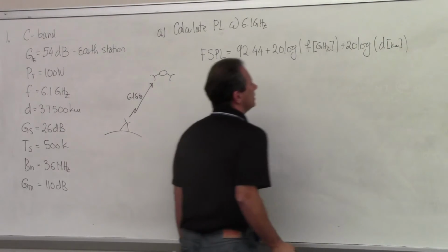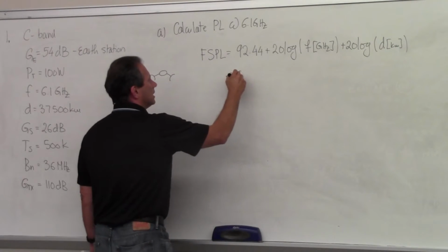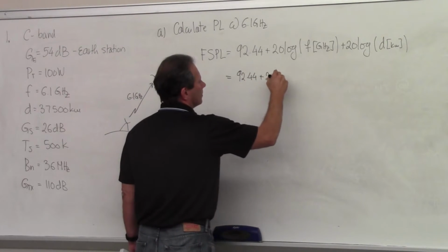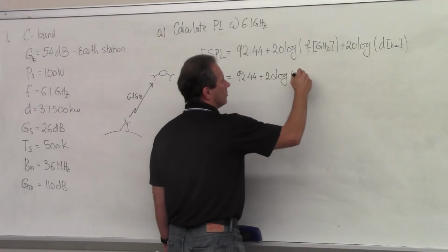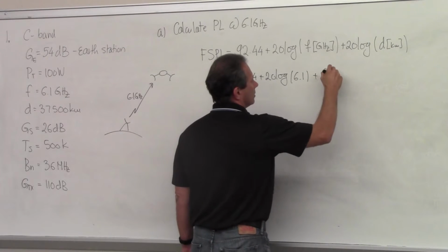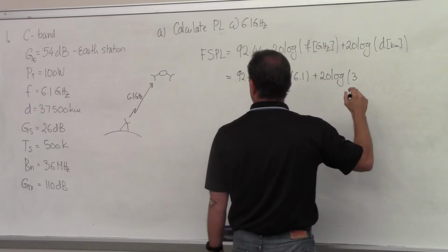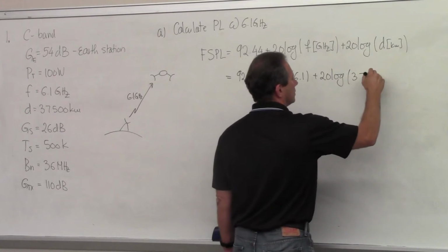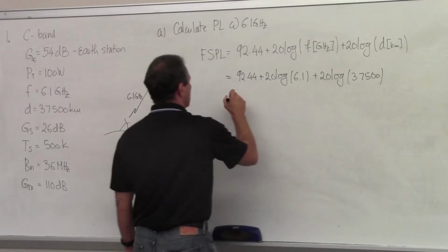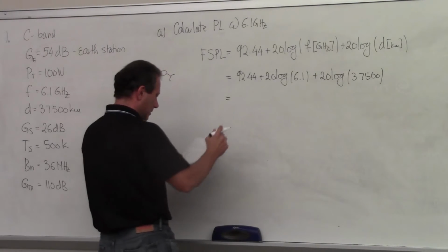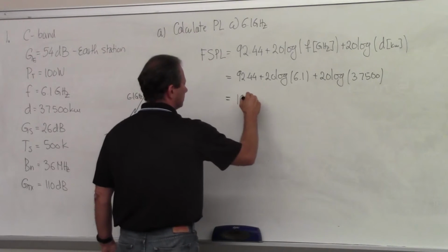In this case, this is 92.44 plus 20 log of 6.1 plus 20 log of 37,500. When I did the calculations, this ended up being 199.62 dB.